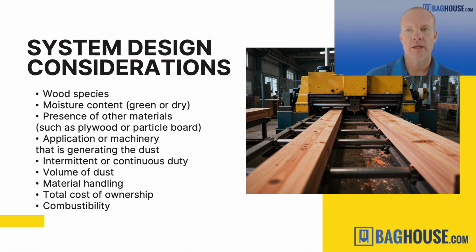Application or machinery: we design a system starting with every single pickup point. So that's every machine in your shop. We would do a layout and we want to start by identifying the size and type of pickup points so we can start sizing the ductwork and eventually sizing the whole dust collection system.